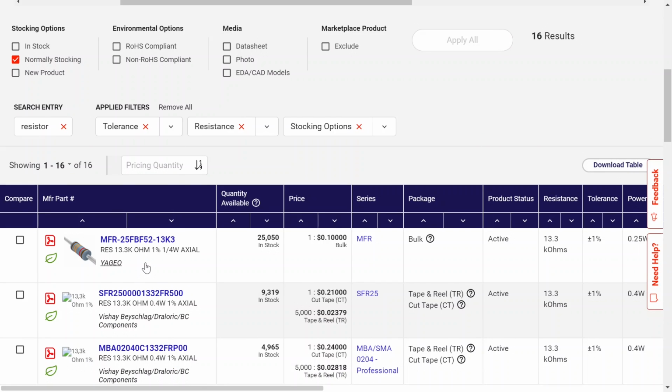So there you have it. Given our desire for an inverting amplifier with a gain of 7 using 1% resistors, it looks like a 93.1K and a 13.3K are our best options. I would argue that that solution is in no way intuitive, and it took a fair amount of work to get there. We first had to calculate the ratios, then we had to walk through the E series that interested us, and then we had to go to our distributor and see which resistors were indeed available.